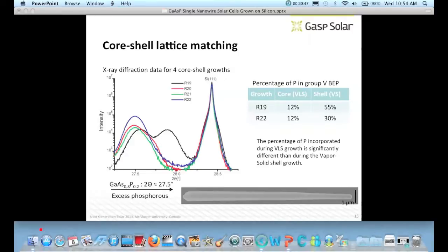It's really huge, this one. The one we're measuring on is not as thick. But what I want to show you with this one is the tapering. This is due to, as I said, their very close proximity. When you grow them, they're very dense on the substrate. So you have the nanowires standing next to each other, and the flux is coming in at an angle. Therefore, you will be growing your shell mostly at the top of the nanowire.